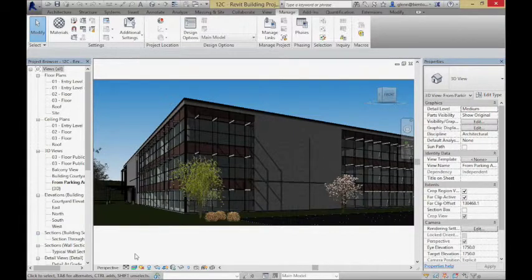You can start to see now there's some degree of shadow being cast by the objects. There's also some degree of materiality that you can see. It's doing a pretty good job of taking the photograph and wrapping it on that. It's not doing a really good job of bouncing the light off the building at this point. That's one step further. So we can start by changing to what's called the realistic appearance, and that gets you one step further.